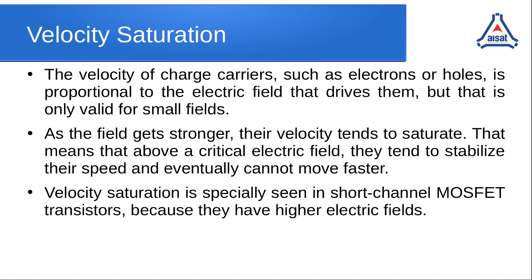Even after increasing the electric field over this critical electric field, the charge carriers cannot move faster. This is called the velocity saturation. And this is specially seen in short channel MOSFET, because they have higher electric fields.